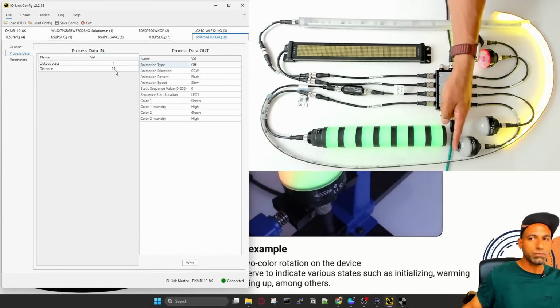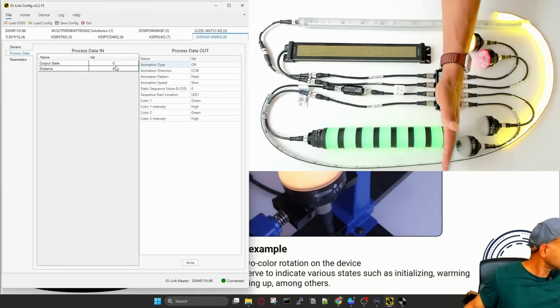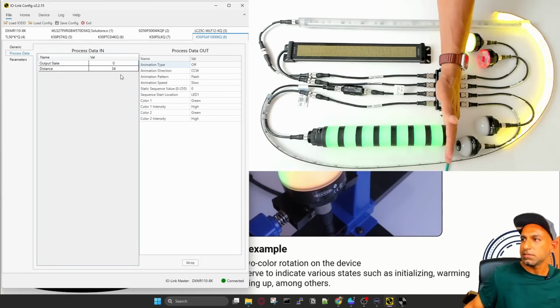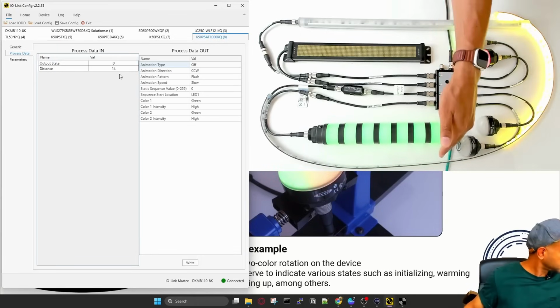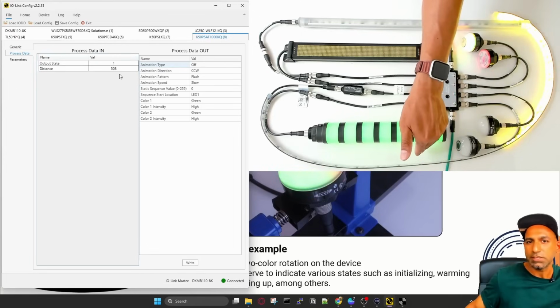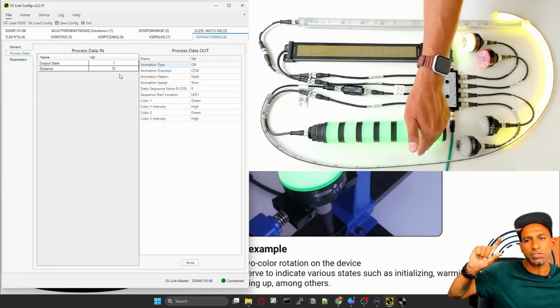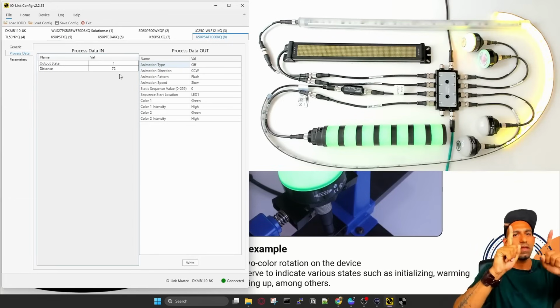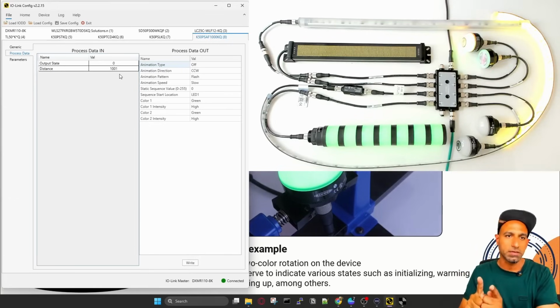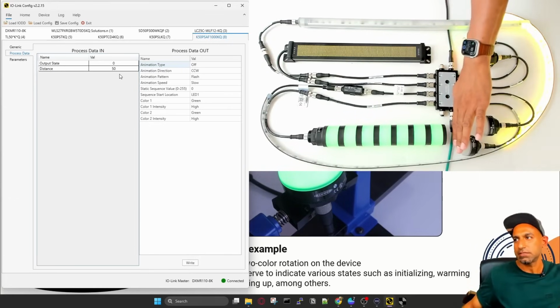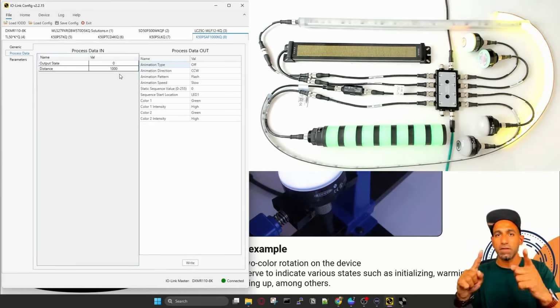And if I touch this one or just bring it closer, you can see its output state is, let me just try to put my hand. So this is showing you the distance, and the output state might have some threshold value. Now it is 1. So it has a threshold that the distance should be, let's say, x, then the output state will be 1, not when you are totally touching it. That's the different output state. But you can configure that as well.